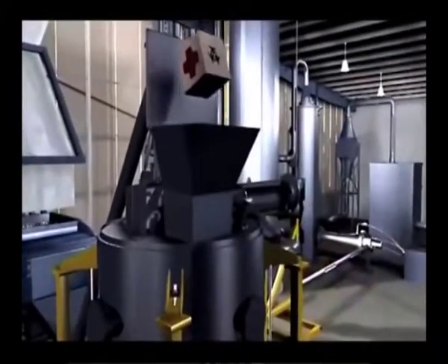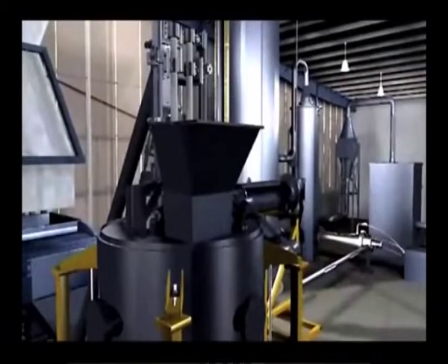Plasma incinerators ionize inert gases via an electric arc between 2 electrodes. This plasma creates an extraordinary amount of heat, ranging from 3000 to 7000 degrees Celsius. The extreme heat can easily break down organic compounds into their basic atoms, which later recombine to form gases such as carbon dioxide. Inorganic material is left as a stable, leach resistant slag. Concerns surrounding plasma incineration include ensuring that gas emissions are minimal and clean before being released to the atmosphere.